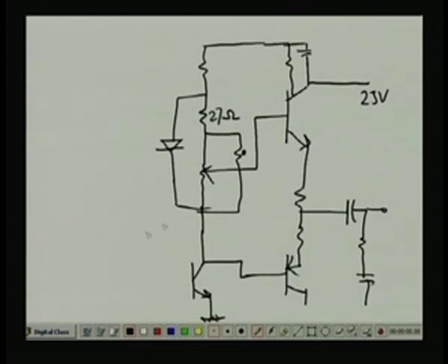The signal will come from these directions and go down there. Now, the reason for this type of circuit is the Q point stability. I need stability, and this is another application of thermistors in electronic circuits. It will make the Q point stable, because due to the resistance and other factors, it may otherwise drift out.